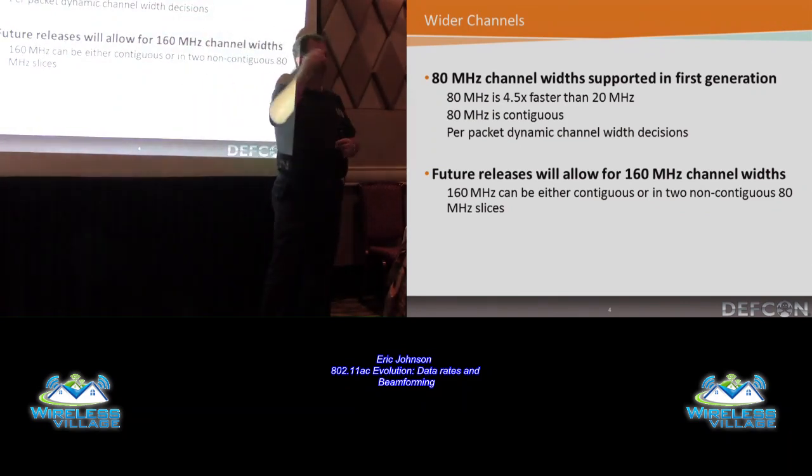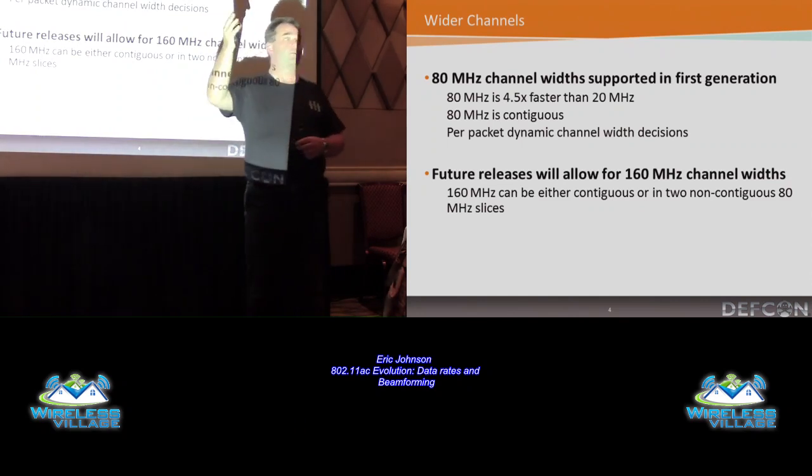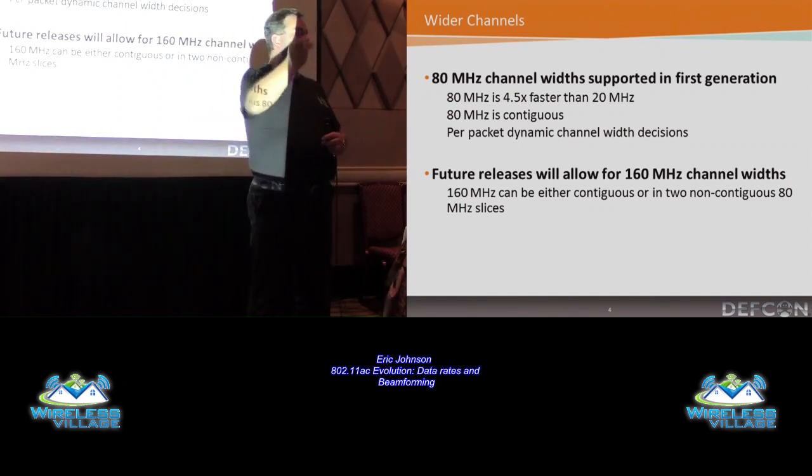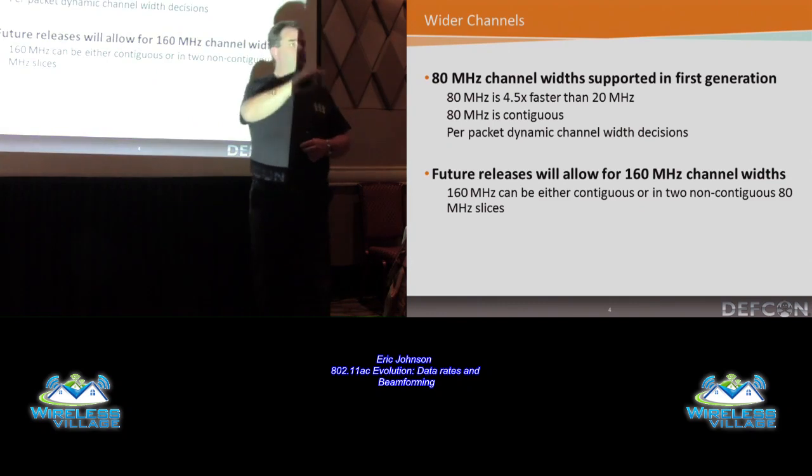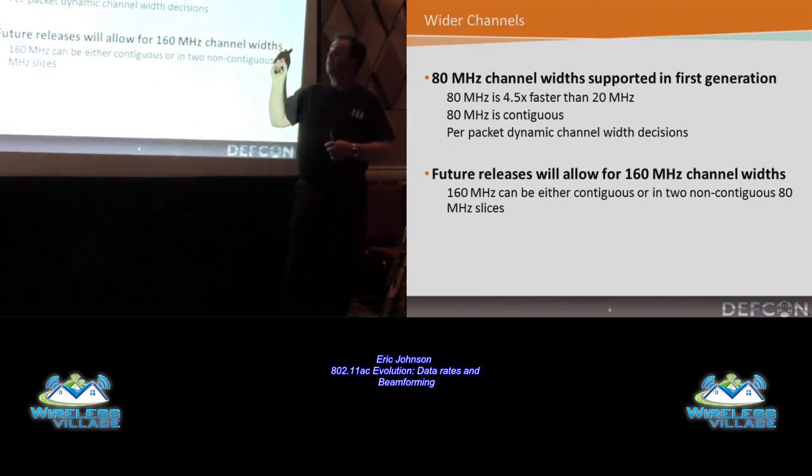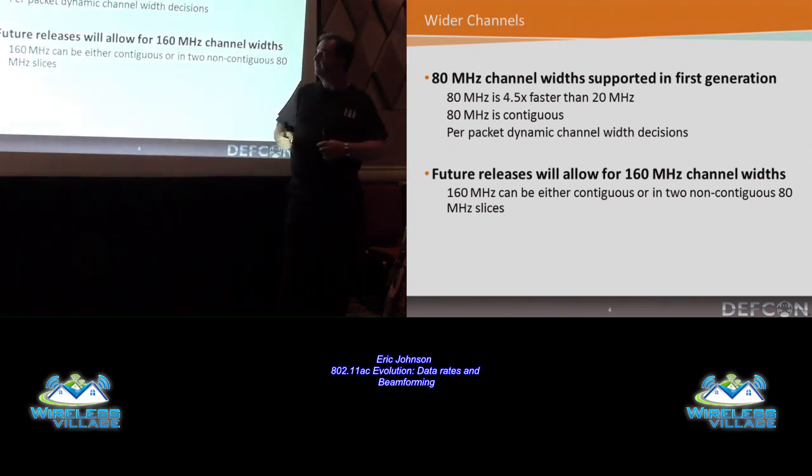This is not like the old days when you talked about what they called turbo mode, where they'd run 2 channels and you'd try to bind them together and it would create all kinds of spectral crap in the middle. This is a clean implementation of an 80 megahertz wide channel.